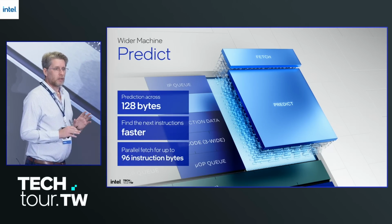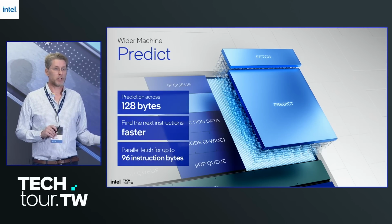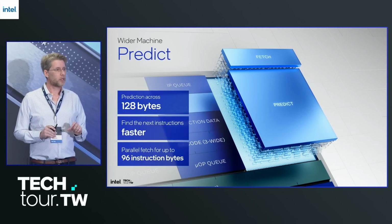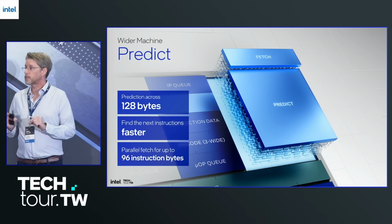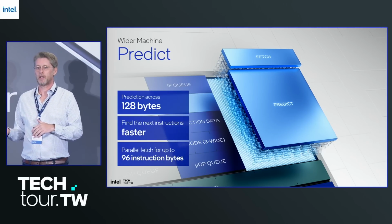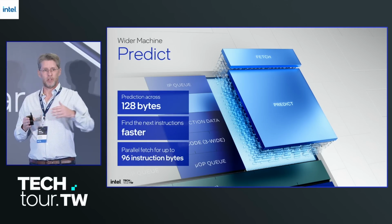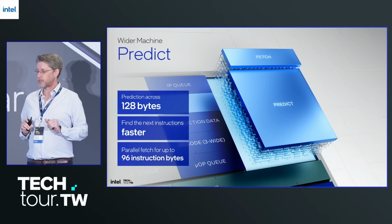On Skymont, we fixed some things to make it more reliable. In Crestmont, we had to start at a specific 128-byte boundary. Sometimes we only got half of that, sometimes only a quarter. On Skymont, it's arbitrary. You can start at any 64-byte boundary. We call this even-odd. Now, no matter where you start, in which cache line, you can look across more. And fundamentally, we're just getting that next instruction quicker.